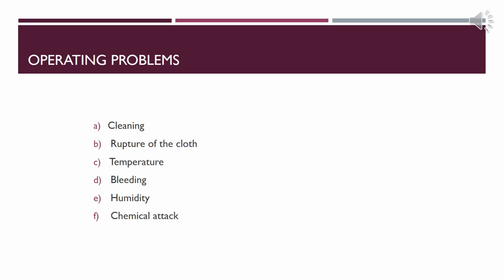Bleeding. This is the penetration of the fabric by fine particles, which is common in fabric filtration. It can occur if the weave is too open or the filter ratio is very high. The solution is to use a double layer material or a thick woven fabric.